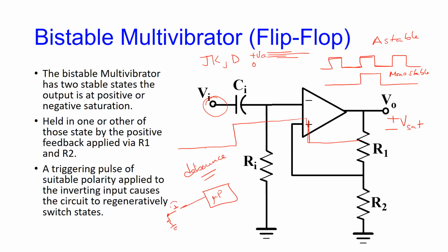Remember, switches are mechanical contacts. So what happens in here, instead of a nice low, going from high to low, what you could get is this kind of juddering on the mechanical contacts of the switch, and they call this bouncing. So in other words, the contact is not a nice low to high or high to low. It goes and then it chatters a little bit before it settles down.